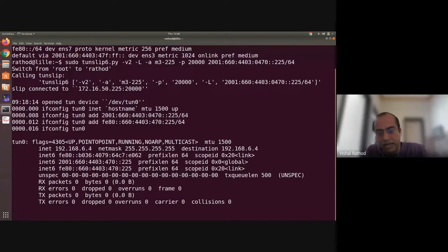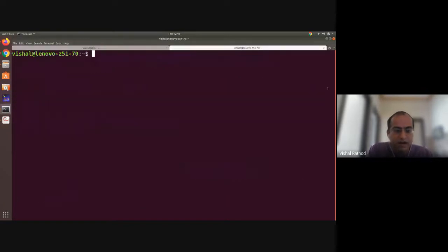Now it is waiting for my connection, right? Open the bridge connection in another terminal because I didn't upload the border router code. Once I upload the border router code, it will show me the IPv6 address. Okay, so let me show you by flashing the border router code.